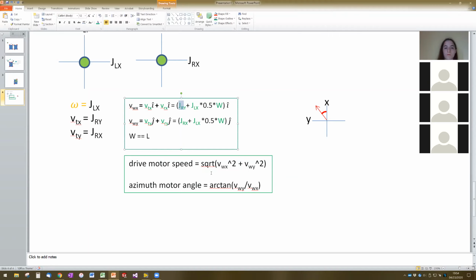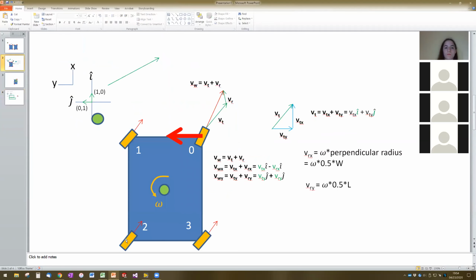And what that's going to look like is you're going to lose orientation control of the robot, because all of a sudden, it'll say that this wheel needs to go at a power of 1.5, and this wheel down here needs to go at a power of 0.9 or something in order to do the exact rotation and translation the driver's telling it to. But this wheel can't go at 1.5, it can only go at 1. And so physically the robot is now going 0.9 in this wheel and 1 here.